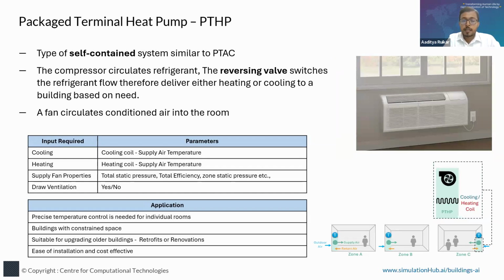Similar to the packaged terminal air conditioner, there is also the packaged terminal heat pump. It is a heat pump which is packaged in one box, self-contained: the compressor, condenser, evaporator, all things in one package. Because of this, it is also very good for retrofitting applications as well as where space is constrained.